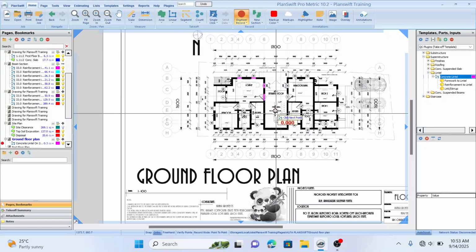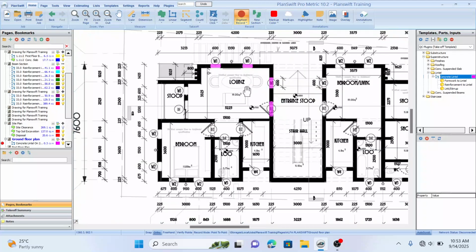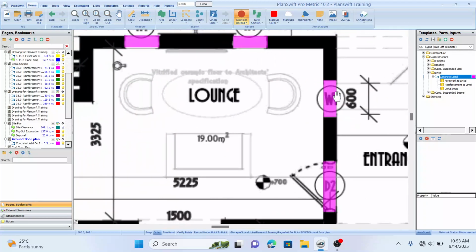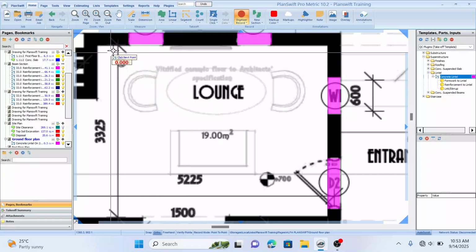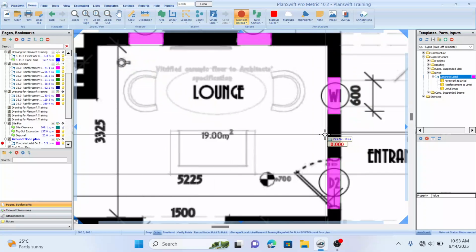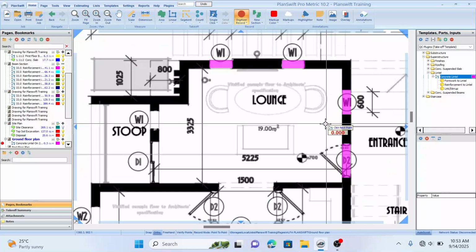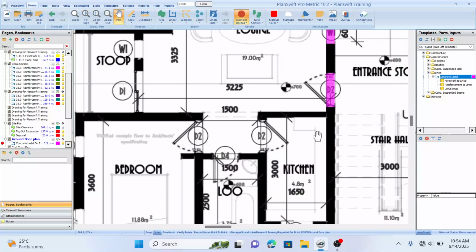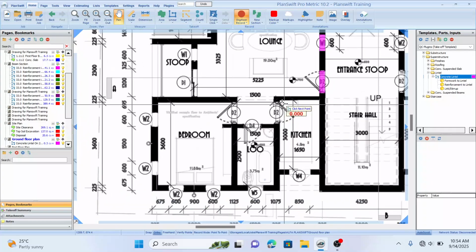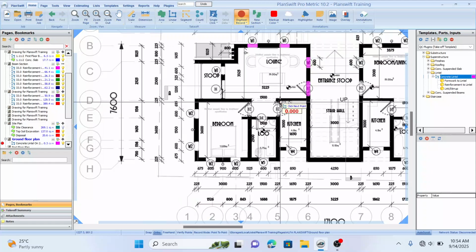Because if the contractor wants to make use of that type of continuous lintel without breakage, and you measure it this way, at the end of the day you under measure. So it's very important that you consult or discuss with other professionals while executing your own work as a quantity surveyor.